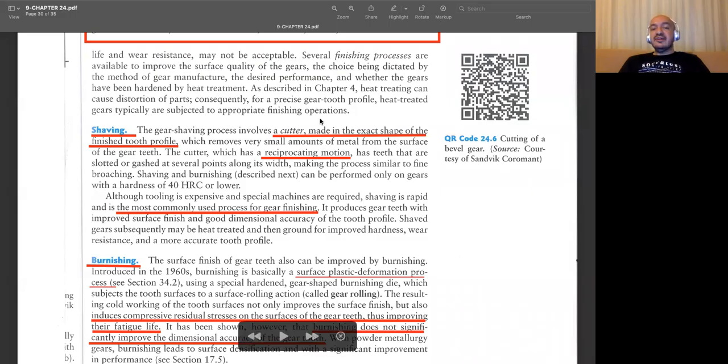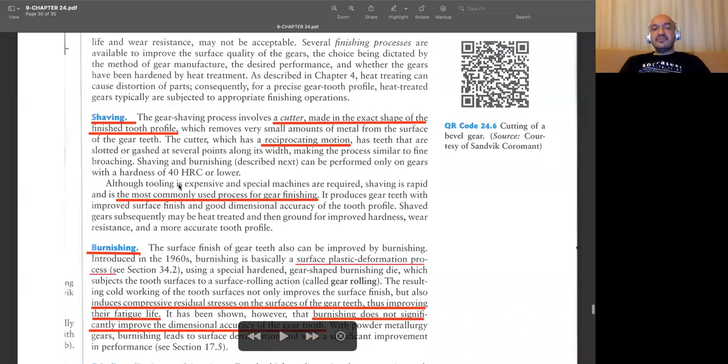But the manufacturing of the cutter is quite expensive, so you should consider it accordingly and try to find a better manufacturer for your cutter and try to decrease its cost. But you know that it's one of the most commonly used gear finishing operations, not complicated, since you simply have a tool which has sharper edges, and by removing less material, you can increase the quality.